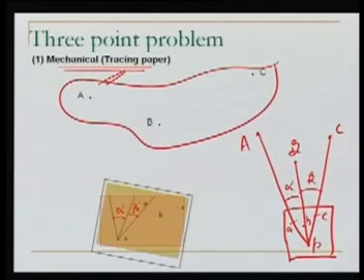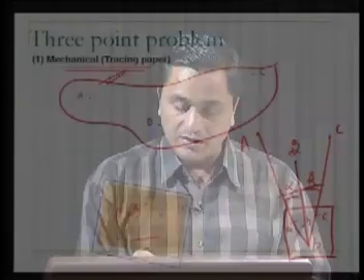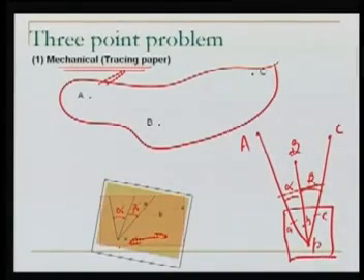And this alpha and beta are the same as the alpha and beta here. Now, why is it so? Because the distance from plane table to those points, control points, is very large. A little bit shift here is not going to matter much. So the alpha and beta, wherever I do on the plane table, will be nearly those values which are the same as the actual alpha and beta. So by doing this, we have realized these two horizontal angles.